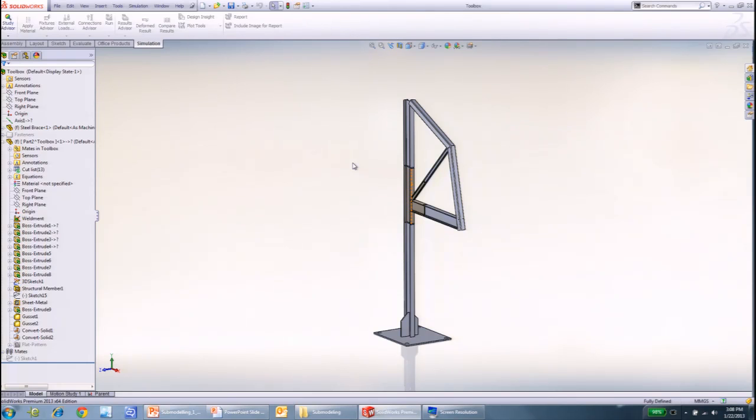You have tapered beams as well, but when we analyze it in simulation, to analyze it quickly, we can simplify it as a 1D line element and give the cross section of the beam instead of doing it as a 3D. Yeah, if you have bolts and nuts and holes and you want all that to be incorporated, you have to either do it as a shell or solid. But if you don't have that, you make it a beam. So people like truss structures and frames, they would just draw sections and just analyze that without the details and make judgments based on that.